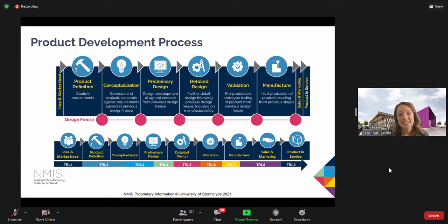You should freeze the design after each successful review in order to ensure everyone is clear on the design intent, especially if there are multiple stakeholders or it's a system design, and that everyone will be aware of any resultant impact, especially with respect to cost and lead time, for any changes made outside of this process.